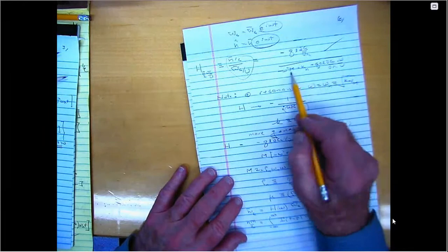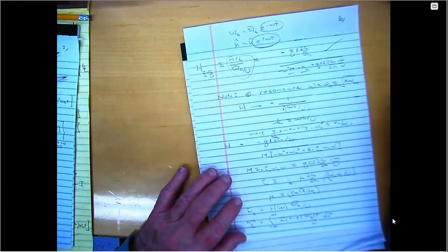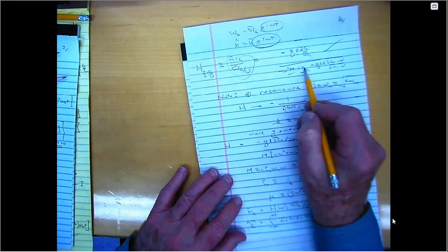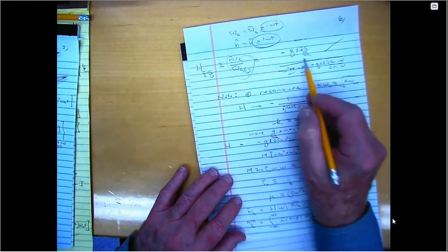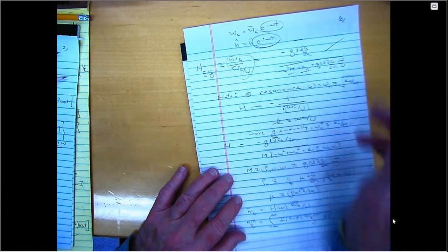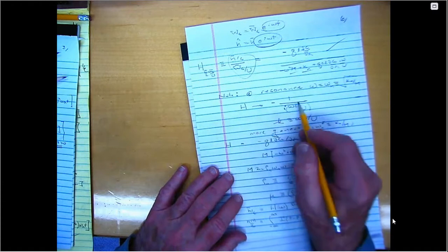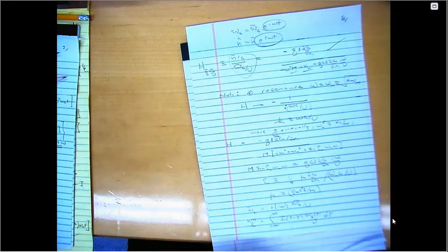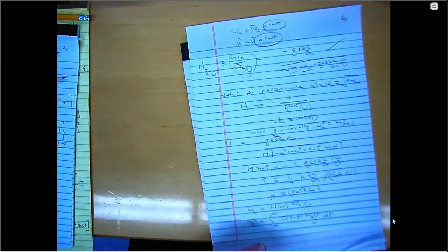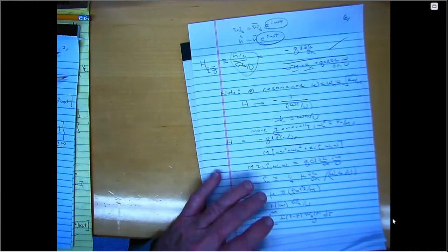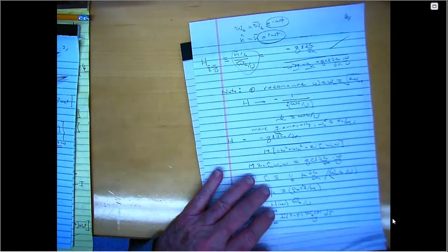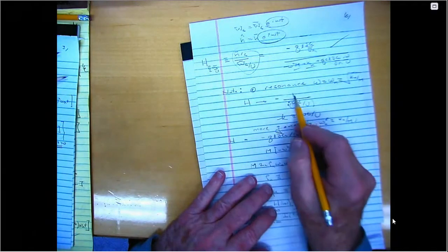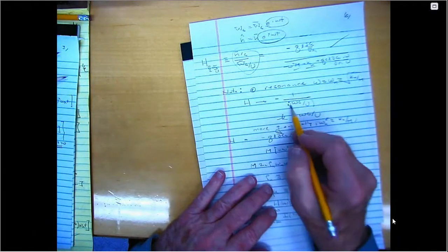At resonance, the inertia term and the stiffness term balance. The resonant frequency is when omega squared is equal to k_h over m. If that happens, notice everything sort of cancels out, and I find that the transfer function at resonance is a minus sign. Remember that minus sign that had to do with the lift is still there. Terrible thing. But that's not the important thing. The important thing is that the transfer function is just 1 over i.